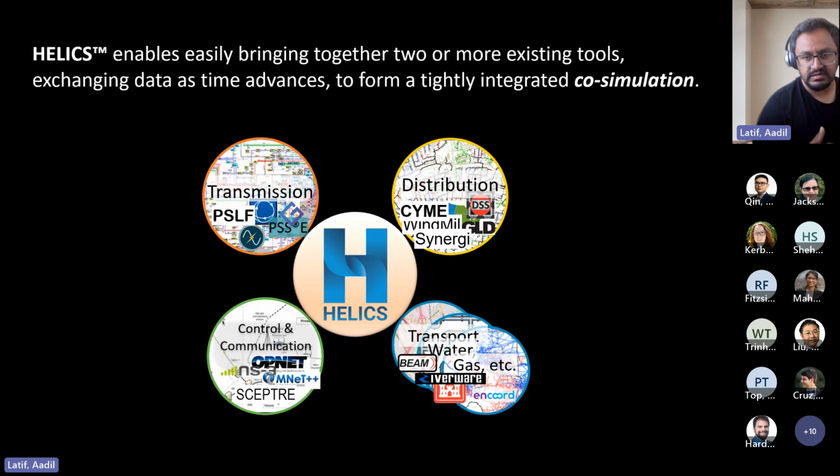But you can actually exchange information between multiple subdomains, and as you do that, you're able to have a much richer understanding of the overall impact of a simulation, right? So you can simulate very rich scenarios without having to, say, reduce the fidelity of your model. So that is typically what would happen if you're looking at the transmission system only simulation. What essentially happens there is you aggregate the distribution model. You've got it represented as one single lump load. So you're not able to see what is inside the distribution model, right?